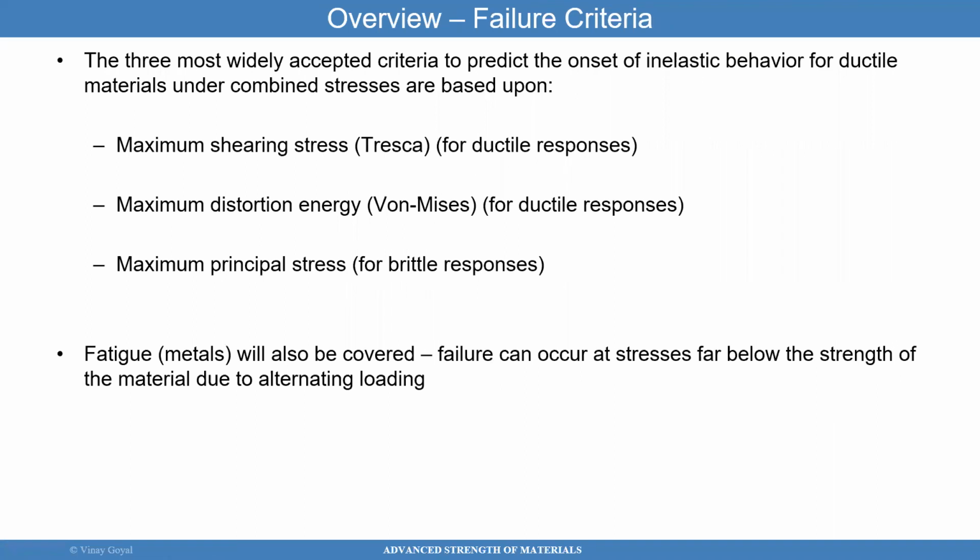There are three widely used inelastic material failure criteria. The first one is the maximum shearing stress criterion, and that's good for ductile responses.